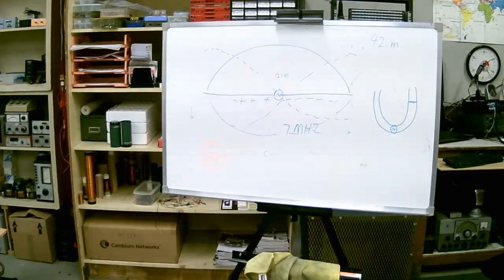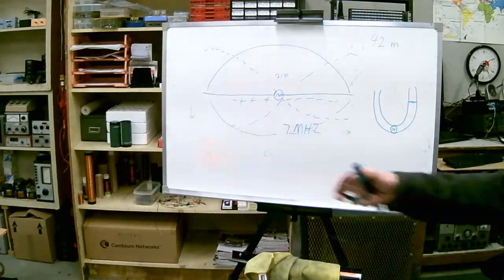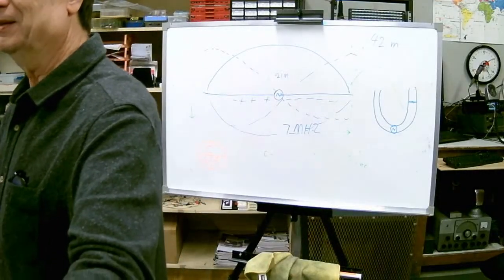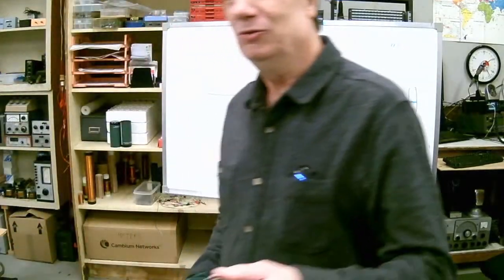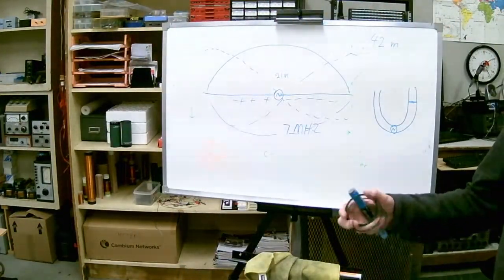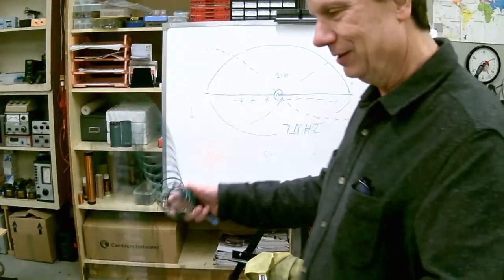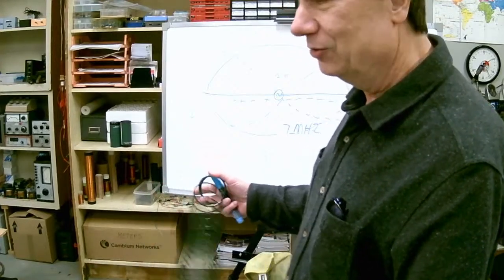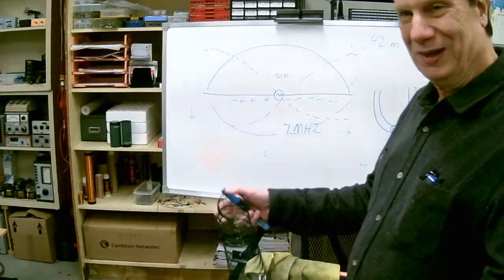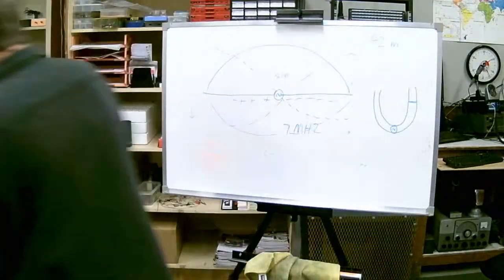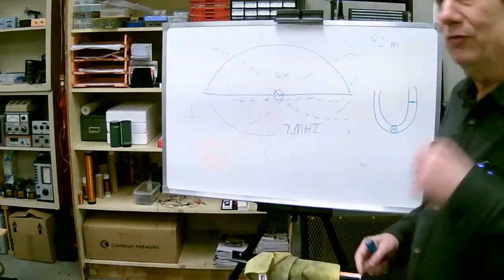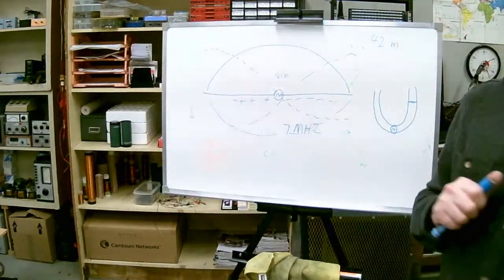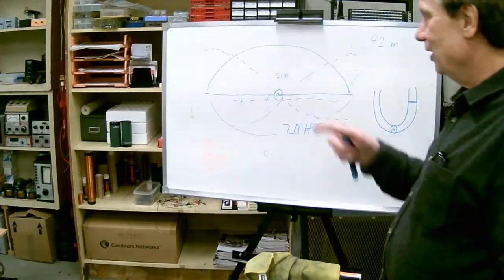And I always have my nice Slinky here to demonstrate that. So there's a half wavelength between. As a musician, you should be very familiar with that. So that's a half wavelength resonating. Pulling at the ends means it can't move because there's nowhere for it to go. So the end is going to be fixed in terms of current. We have no current flowing at the ends. We do have opposite voltage at the ends here. So we have a generator here, we have current flowing, and we have voltage across it.